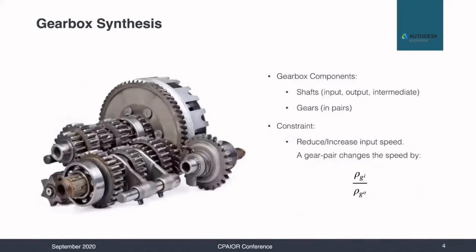A gearbox is a mechanical system that transmits and converts an input speed to one or multiple output speeds by means of a series of rotating elements called shafts and gears. A power source rotates the input shaft with an input velocity, which in turn rotates the next connected shafts, propagating the speed throughout the gearbox and towards the output. Pairs of shafts are connected through gear pairs with different radii. The size of the gear's radii determines the speed change between the connected shafts.